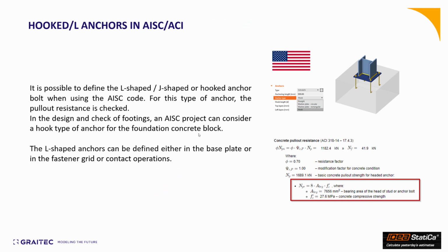Another addition in this new version is the addition of L-shaped or hooked anchors when you're defining the base plate operation. We had all of those before, and now we have this hook option that you will have full control over. Again, this tool right now is based on the American code, ACI, but we are planning to also bring it for Canadian codes based on A23 as well. The software is also able to apply all of the required code checks in case you have defined these kinds of anchors.